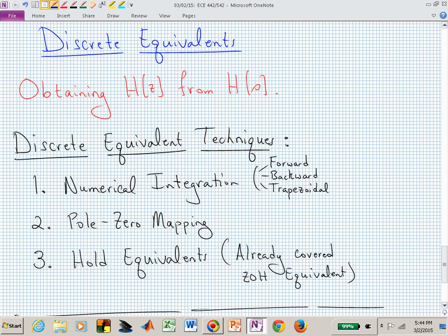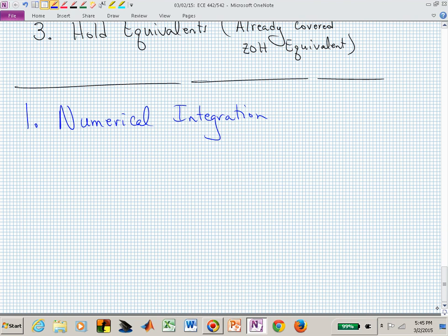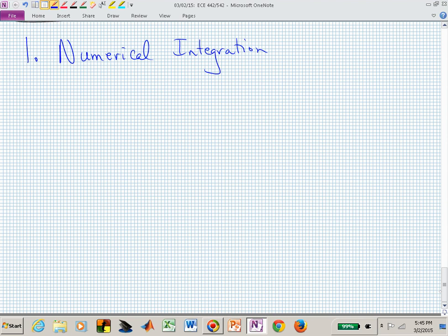And we want to today derive that lump of parameters, sampling period, Z's and coefficients, that we will now place everywhere we have an S. So if we had an S squared, we would put that lump of parameters in where S was and square it, and then end up with some transfer function in terms of Z. We've now eliminated the S's. That's what we want to do in technique number 1. Let's then look at what that is. That's technique number 1, numerical integration.